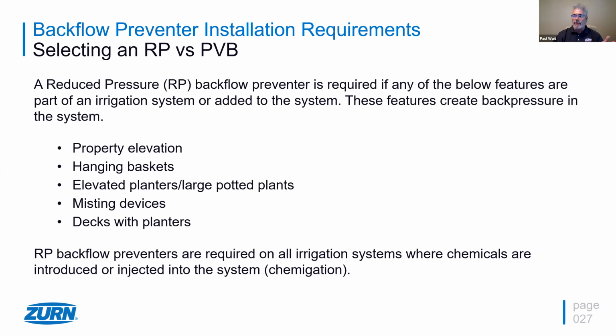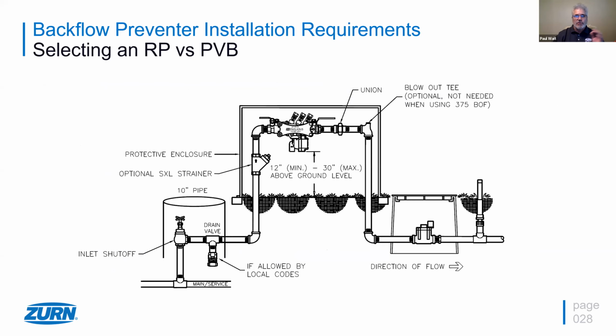And let's just take a peek back at the RP again: 12 inches minimum from the bottom of the relief valve. That's a physical dimension on the RP associated with the product, not an application situation. So this makes it ideal for any installation on any application. And yes, it does cost a little more, but it certainly is the direction that most codes are going, and most applications are requiring in those situations that we just covered.